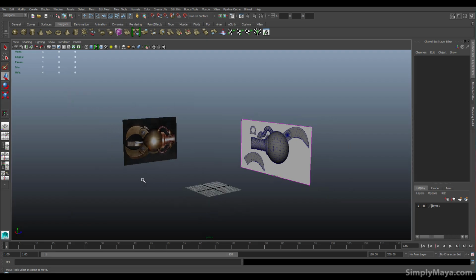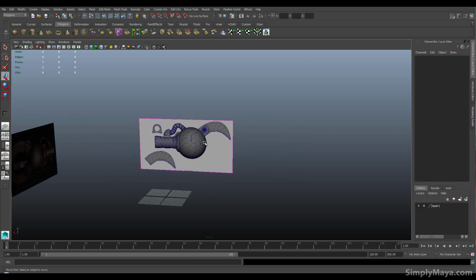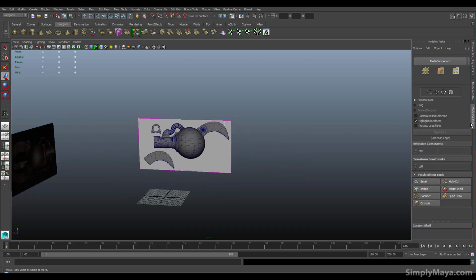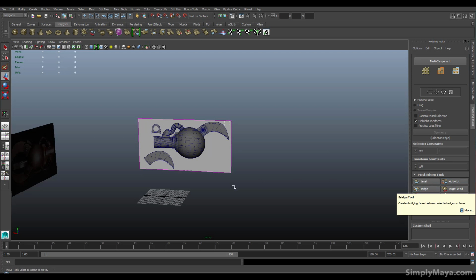Okay, so depending on your version of Maya will depend on how you'll need to do this. I'll also be using the modeling toolkit with this, which is now available in Maya 2015 and above. And obviously, if you're in the normal version, you'll have to use the equivalent Maya tool. So for multi-cut, you'd use insert edge loop, or the split poly tool. Bridge and bevel are about the same, although I would say the new tools in Maya 2015, the bevel especially, work quite a bit better.